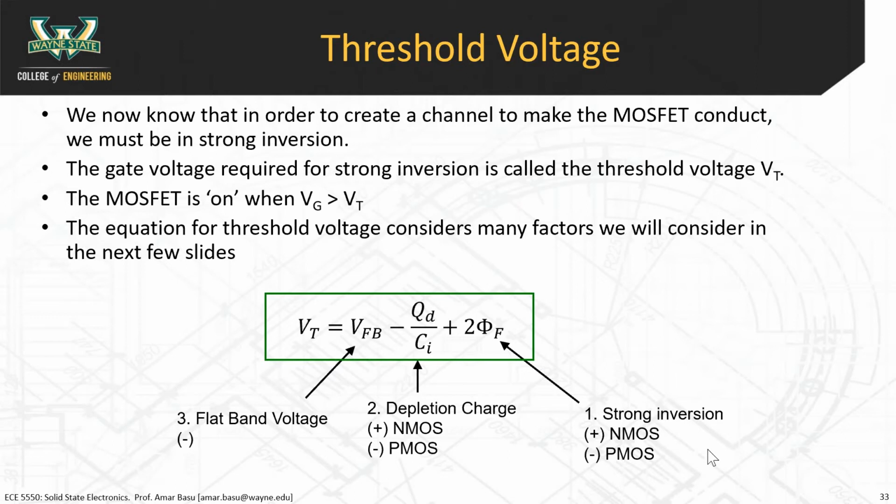A third practical issue is that the threshold voltages have to be uniform for all the MOSFETs in your system. You figure one chip, okay, we went over this at the beginning of the module. A typical chip has something like a few billion transistors. An Intel multi-core processor has a few billion transistors.